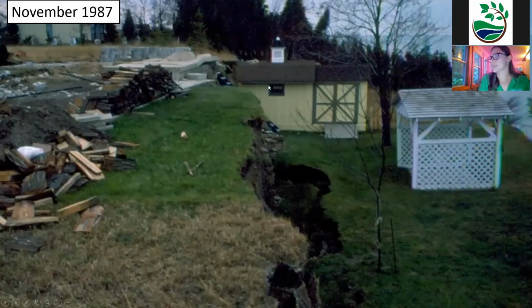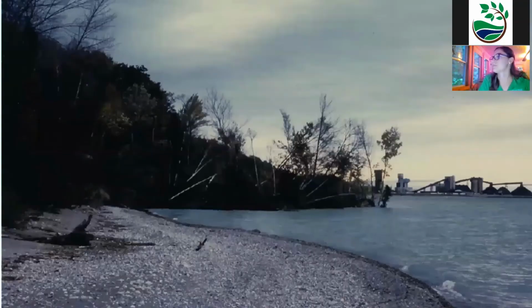And again, we have that structure that was repaired and moved back. And then we have this shed structure that was actually just on the right side of the failure, and it happened to be okay. But just to give you a sense of how big these can be, in conversation with people that were around when this failure happened, it was about 500 meters long, or 547 yards in length. And the drop was about 3 meters or 10 feet. So again, these are pretty dramatic, and they can be pretty large in scale, and the drop off is pretty steep. And so that is what a rotational failure looks like.